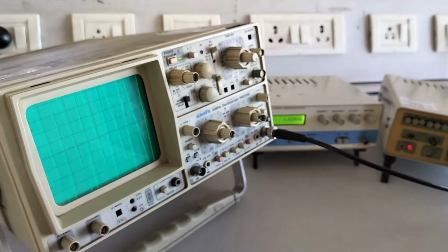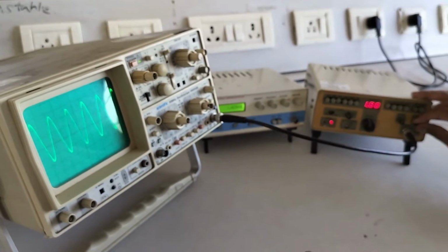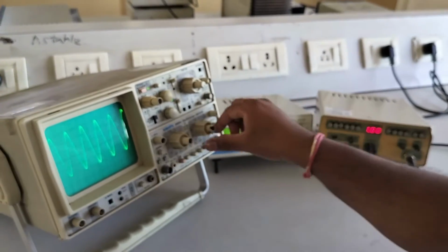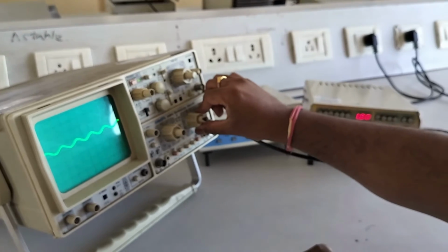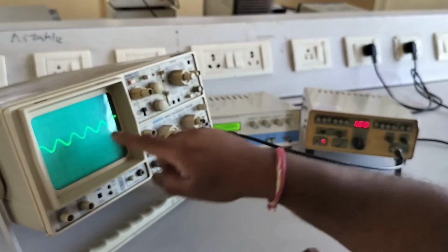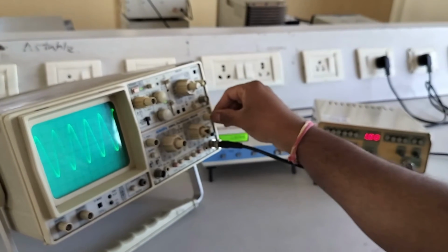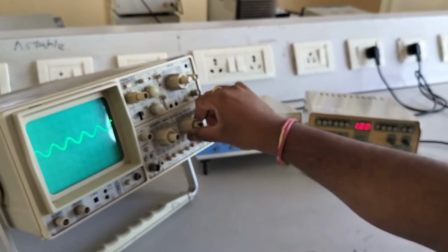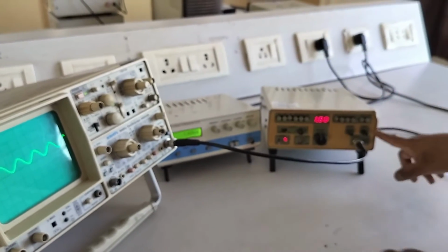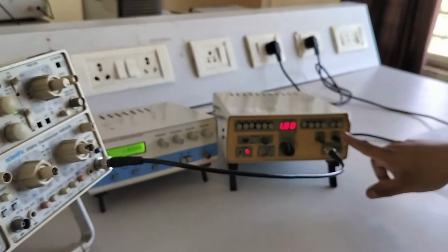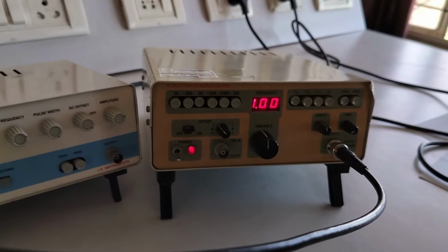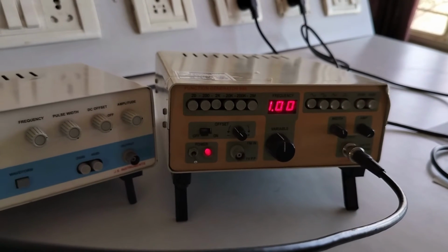See here, adjust the amplitude. If the amplitude is like that, you reduce and adjust it so that the signal covers 1, 2, 3, 4, 5 divisions. 0.1 is there. Again, if you come to 0.5, it is one division. If you keep the volts per division at 0.5, it covers one division. At 0.1, it covers 5 divisions. It is one and the same. It is only a multiplier. So the amplitude adjustment, I have to vary with the help of this amplitude knob. This is actually the main thing. Here it is only an output device, where you can observe the signals.